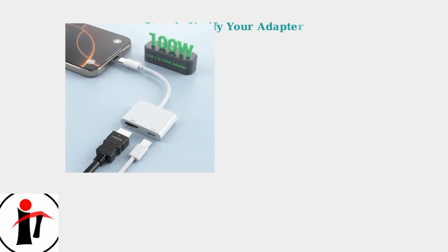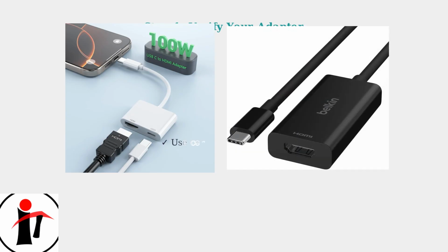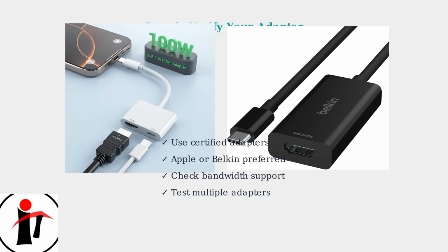The issues often stem from the complex interaction between hardware adapters, display protocols, and macOS display drivers working together in the system architecture. The first and most critical step is verifying your adapter. Many connectivity issues stem from using incompatible or low-quality adapters. Use certified USB-C to HDMI adapters from trusted brands like Apple or Belkin. These adapters must support the required bandwidth for your monitor's resolution.